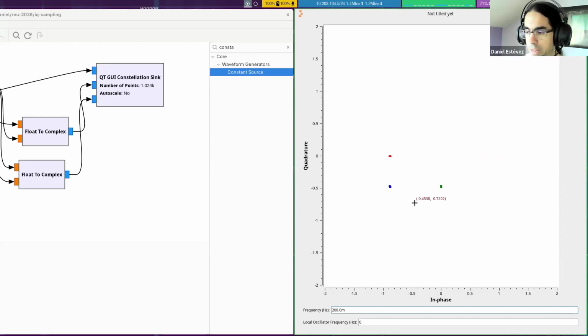So I think this is a good explanation of why, if we want to work with the concept of negative frequencies, real signals don't actually have them. They cannot distinguish between negative and positive frequencies, but complex signals can, because they have real and imaginary parts and can be rotating in one direction or the other. Questions about this example?